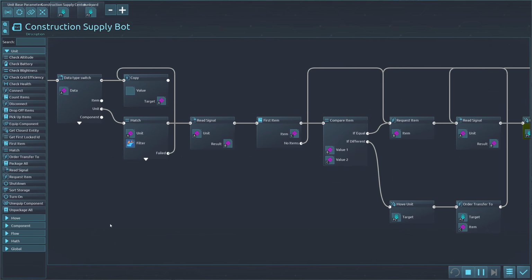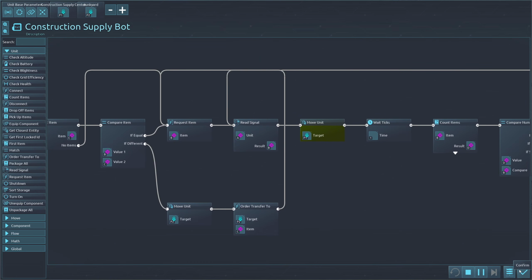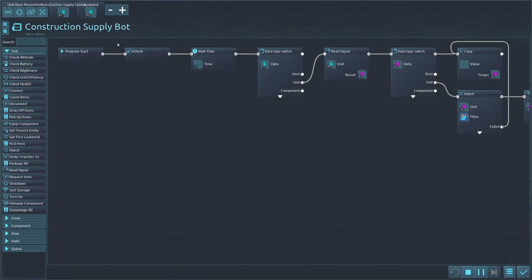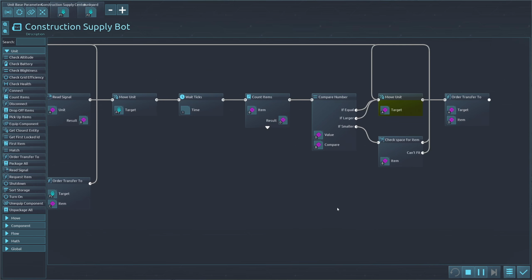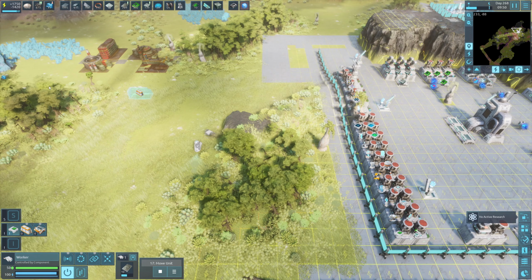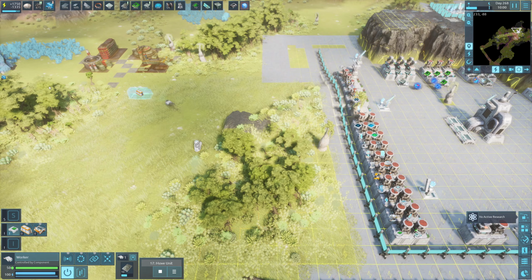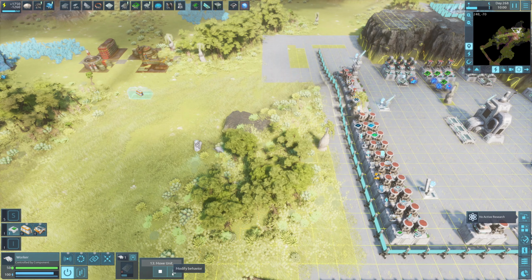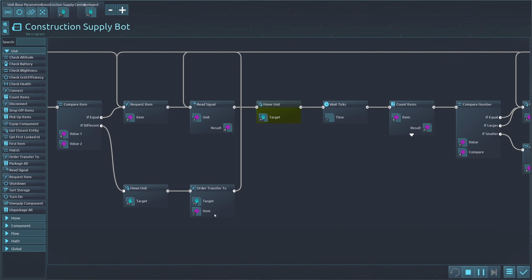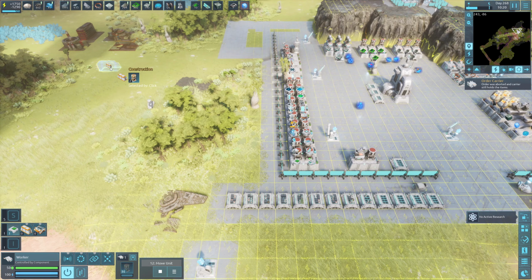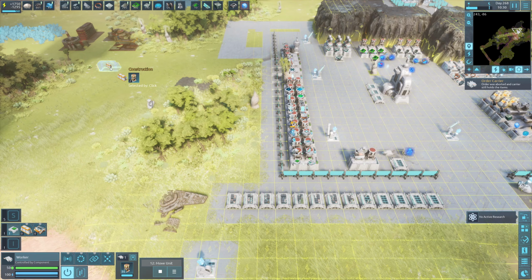Now, as it's returning back home, just in case, well, it first will go home. We can replace the move with move async or asynchronous. In the case of whenever there is in fact fulfillment of that request, it will basically start moving in a different way. Now, it fulfilled the request, it's moving home, and let's swap these two in places, just to make sure it won't grab items that we don't want.